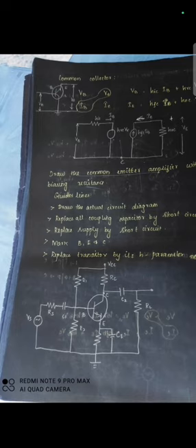First draw the symbol with biasing resistors. Okay, so as I explained earlier, what is the purpose of biasing resistor, right? Then why we are choosing this common emitter as an amplifier. Okay, now we will couple the source voltage and source resistor by using the coupling capacitor C1 and our load resistor using the coupling capacitor C2.